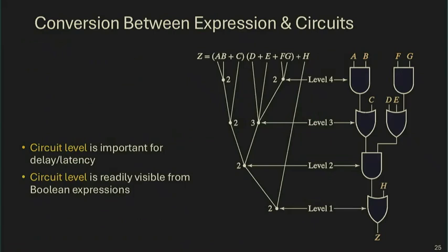All right, and we're not going to care about any of those in this class. We care about a basic combinational or sequential implementation. And the way we measure delay and area is as follows. Given a circuit, you can easily count the number of gates. Starting from that Boolean expression, you can hierarchically decompose it. At the top level, it's an OR function between h and another function. The next function is the AND between two sums. So you can keep decomposing it until you reach individual gates and individual variables.